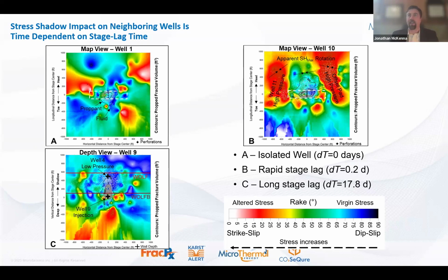But with rigidity, as you get more brittle rock, it should crack better than less rigid rock. If it cracks more, then we should hear good acoustic emissions, so we should see good microseismic energy.